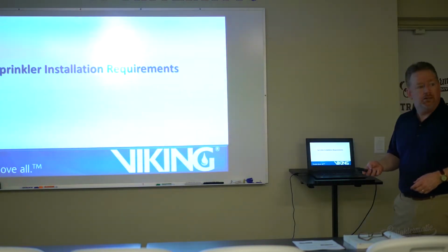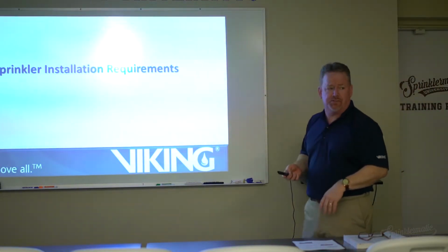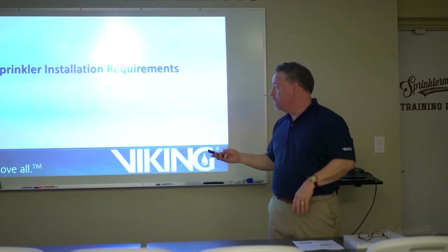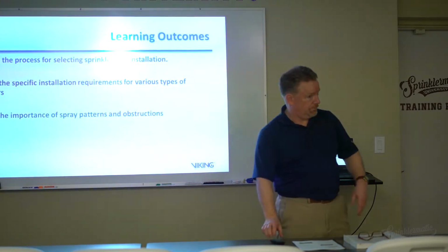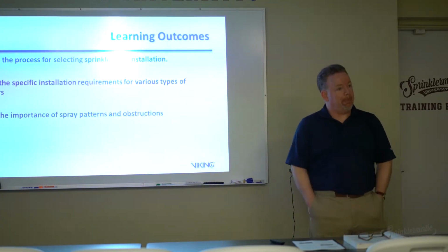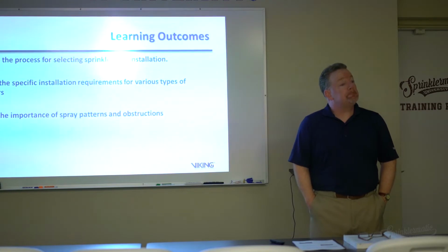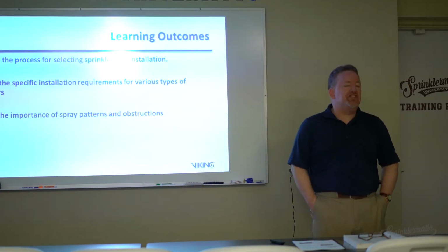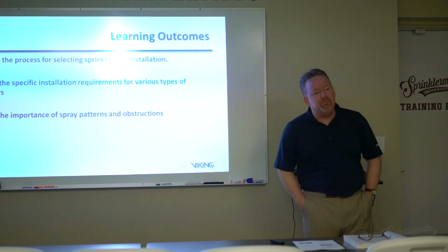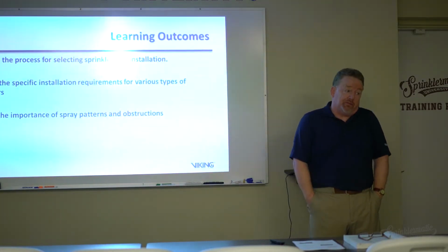Can I ask you a question? Sure, you may ask many questions if you'd like. If you design a building for a light hazard occupancy, obviously you're limited to 4 or 5 sprinkler heads that are available. Well, there's more than that. They just need to be quick response. Viking builds many quick response sprinklers. It's just that you have to use them.